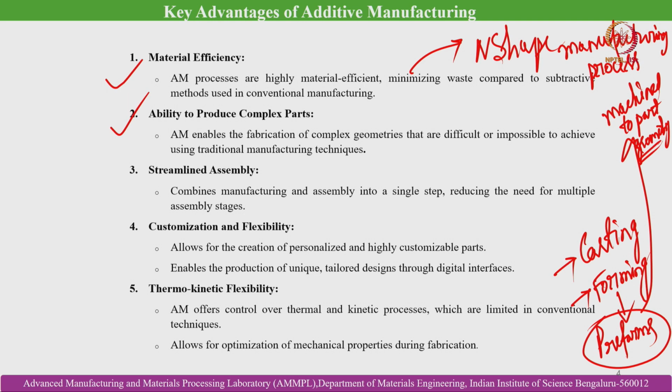In case of casting, the cast part is developed directly by solidification of the liquid melt, and in case of powder metallurgy, it is the green compact, the powder preform, which then needs to be cured or sintered to arrive at the final part. So, out comes the component.